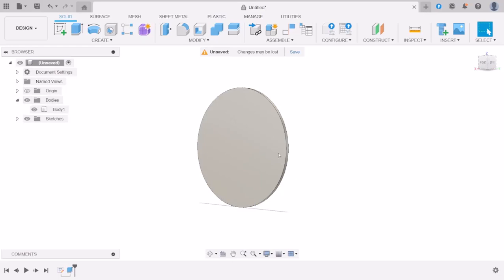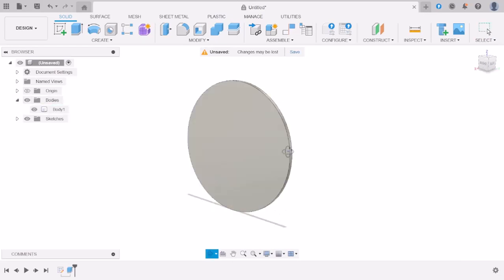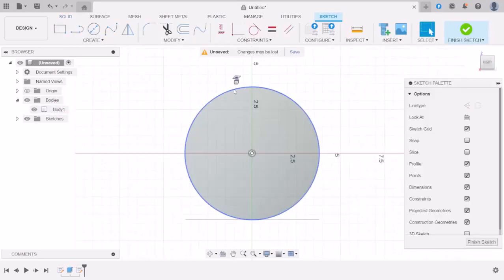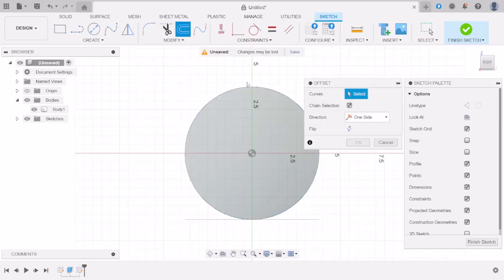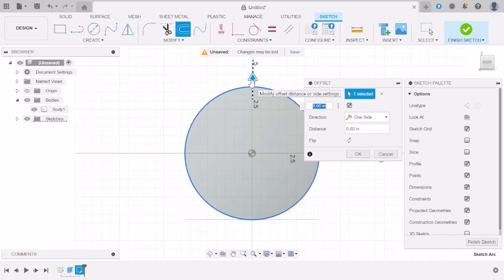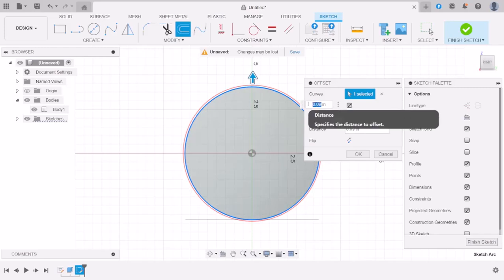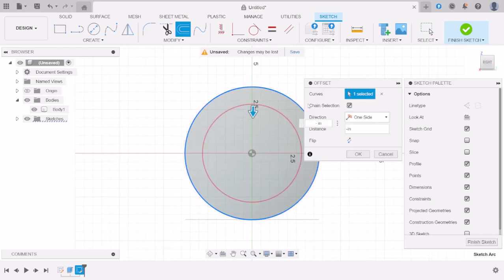And then let's draw on this same body. Let's see what I'll do here. I can use one of the secondary tools to modify, which is offset. I'd offset this circle, and watch, I can drag this top down anywhere, or I can give it a number on this dialog box here. So I'll do a negative 0.3, or let us do 0.4, negative 0.4, and we say okay.